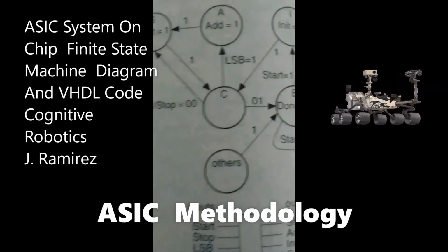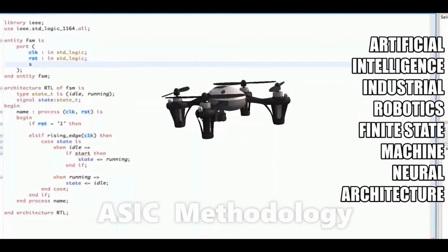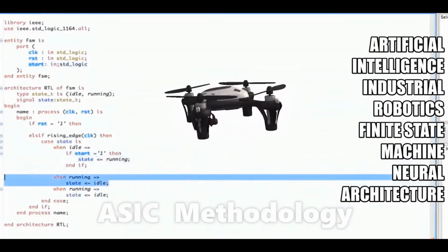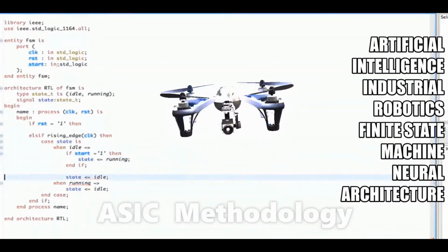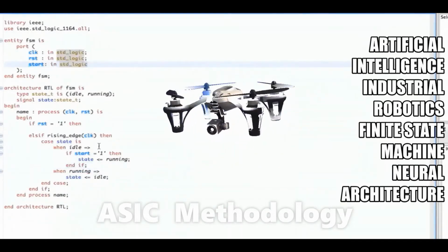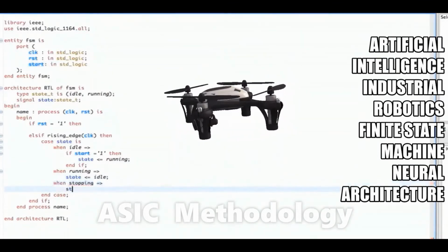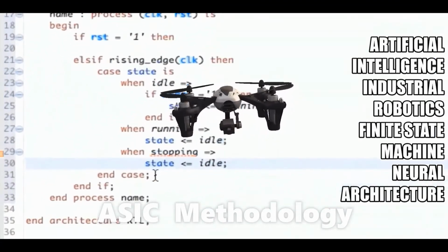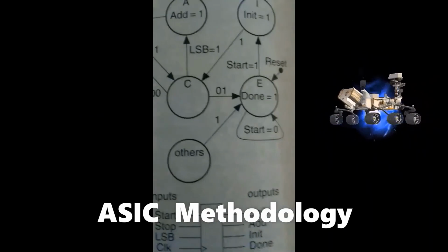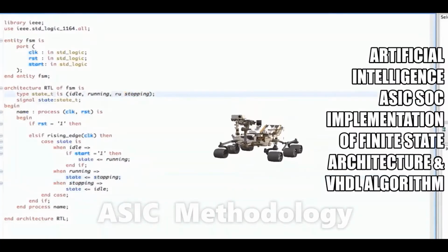The finite state machine, FSM, is a mathematical model paradigm whose output is dependent not only on the current state of the input, but also on past input and output values. The state machines generated in VHDL, as I have presented in this video, are clocked processes whose outputs are controlled by the value of a state signal. The state signal serves as an internal memory of what happened in the previous iteration.